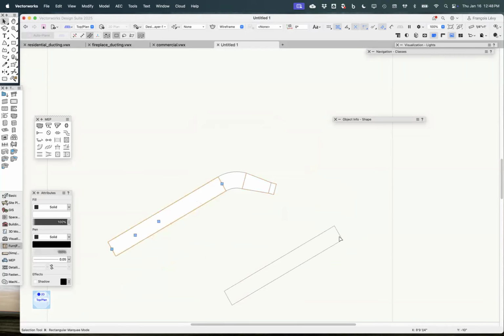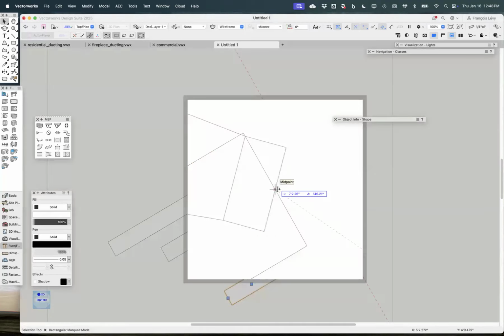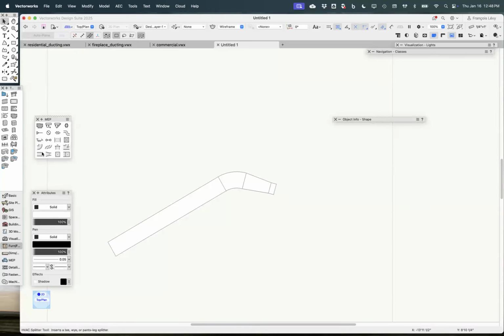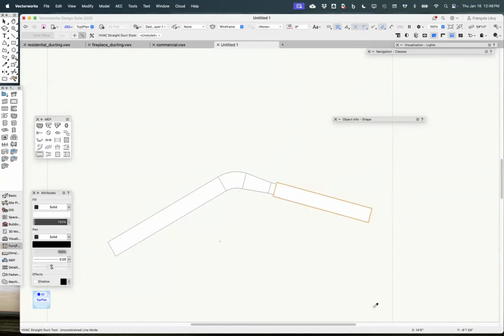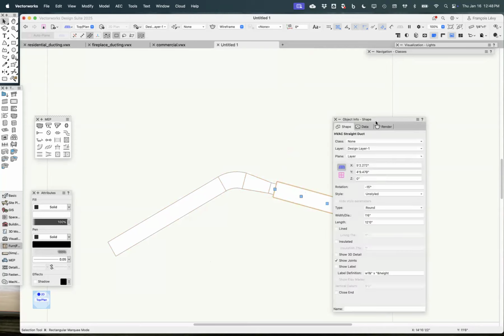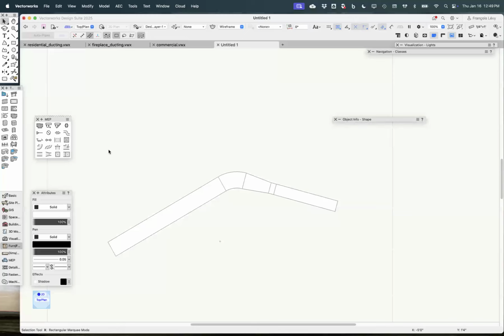I can do this. I can take that duct, right? Or I could just draw a horizontal duct off of that, right? And I could pick up these attributes and drop them on that one, but I can't change the attribute. These are actually different objects, right? They're all called HVAC ducts, but they're just different objects. So then I can change this one to 12 and give it a length of 6 feet. Right? And then at the end, I can go ahead and place a diffuser here.